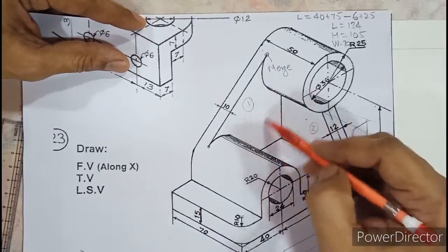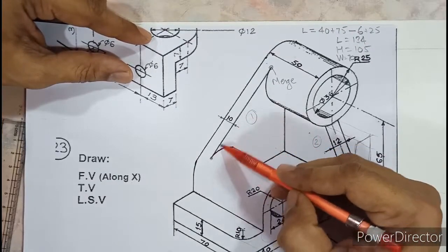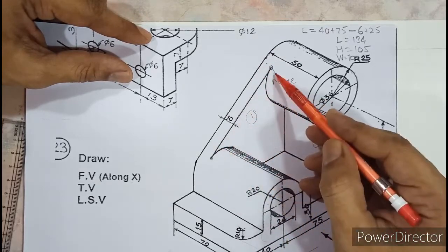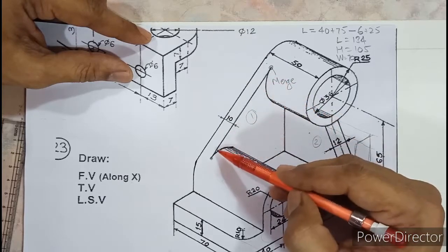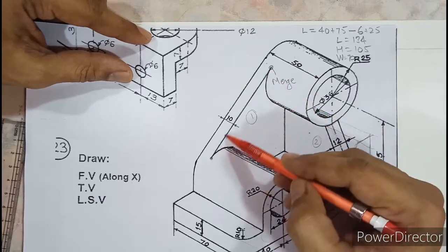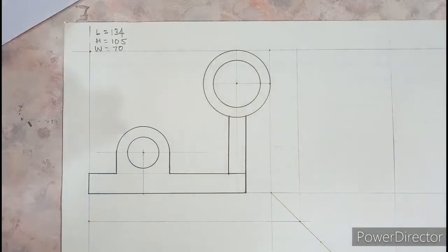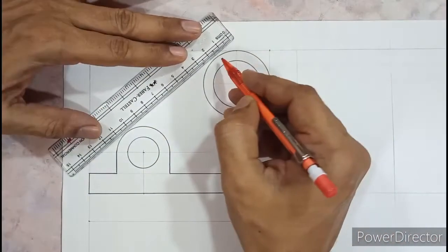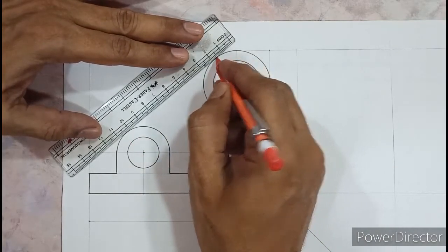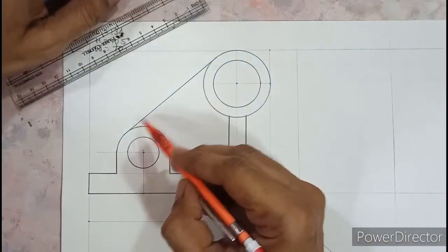So let us try to analyze rib number 1 from the front view. This rib, if you observe, you can see this edge. You cannot see the behind edge. You can see the front edge. Whenever you see this kind of merge point, you have to understand that this rib is tangent with both the circles. Okay, so this rib has to be tangent with both the cylinders. So how to draw that? Very simple. This is your scale. You align tangent with the outer circle and with the outer semicircle. You align tangent to both and then draw a dark line like this. So that is how this rib number 1 is ready.